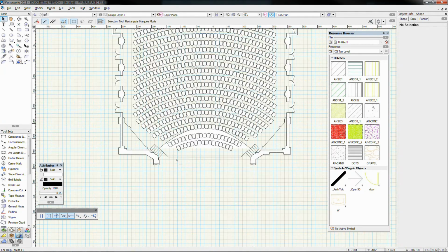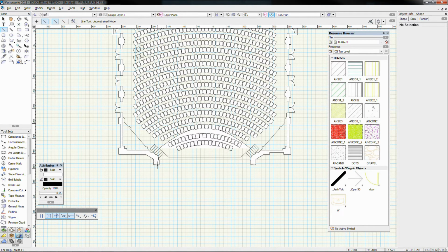Now across the pros here, that's from here to here where I know the stage is. I'm just going to measure that out from here across to here, and you can see we've only got 302 mil, which means this was probably at a 1/50 scale when I brought it in. That's why you've got to scale it up first. So let's say that we've got 302 across here.